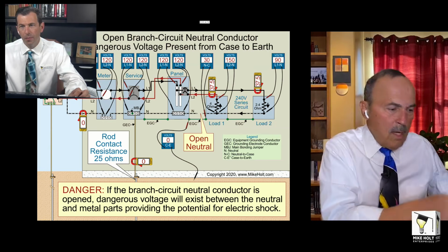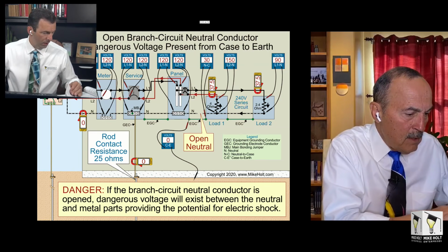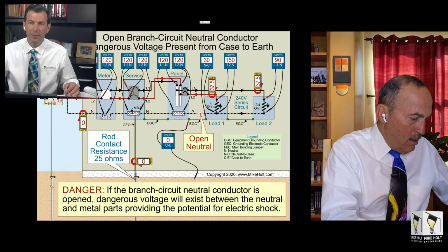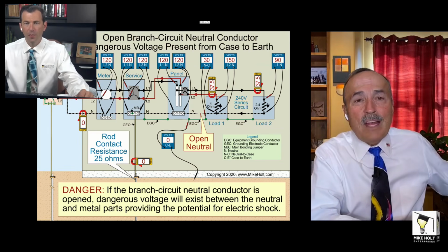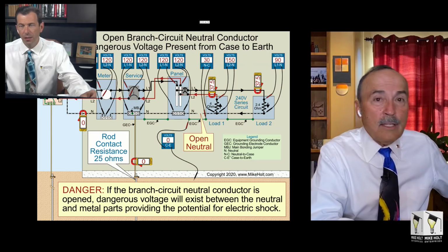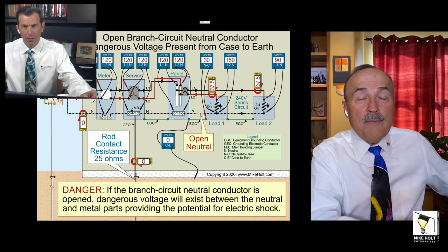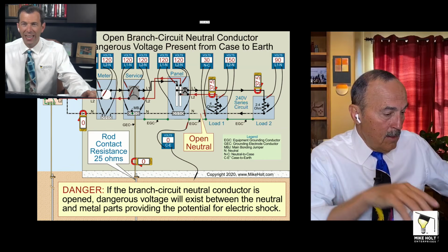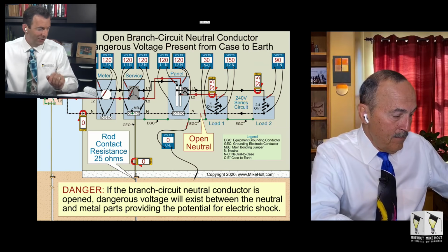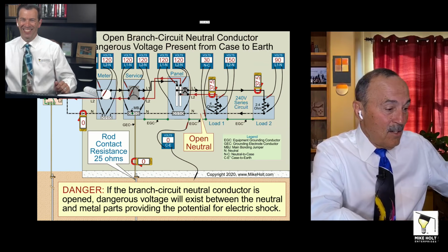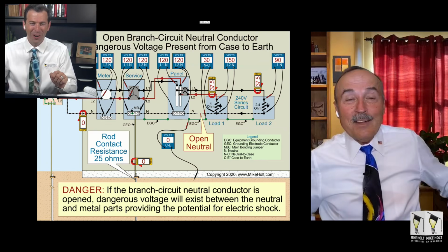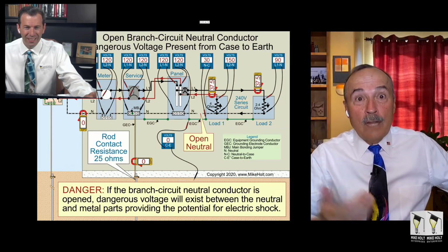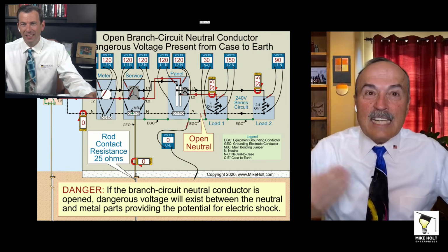What's 314.40 that I messed up? 314.40 is metal boxes, conduit bodies, and fittings, construction specifications. Which says you have to have a grounding terminal. Right. So 314.40(D) says you need to have a grounding terminal for a cover. I was actually agreeing with you and reading the same thing that you were reading until Don said that, and I was like, oh. So look, D is on the other side of the page. That's the first time I've actually made that mistake, but on video of all times, live. I could have edited this out if this was at a studio.